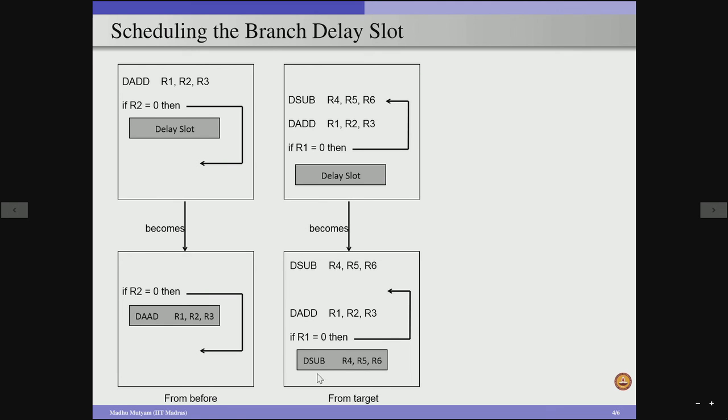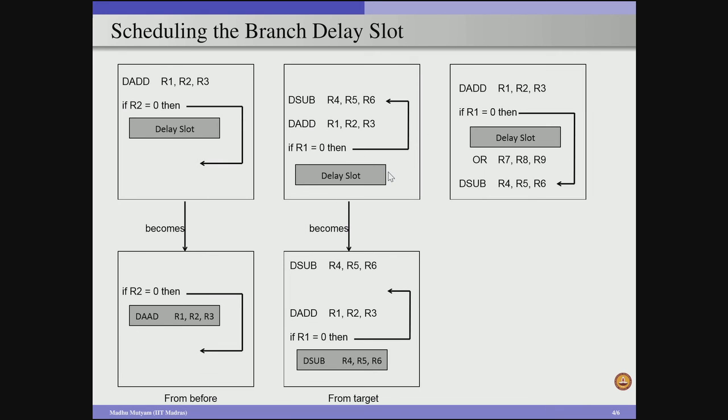So effectively, if the branch is not taken in this scenario, we are going to waste one pipeline cycle, but if the branch is taken, then we are not wasting any cycles and we are getting useful computation. So compared to the first technique, this is not going to give you that much performance improvement, but it will give you performance improvement as long as branches are going to take place. Effectively, if most of our branches are going to take place with high probability, then we can implement this type of technique in our code. Consider an example here.